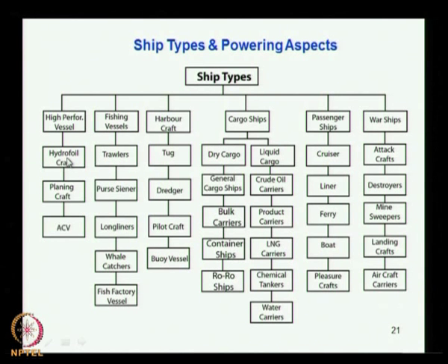When it comes to hydrofoil, again you have a displacement mode because initially it is fully waterborne. So it has to attain a threshold speed so that the velocity of flow to the underwater foil is sufficient to generate a lift and push the vessel up. So that power also should be estimated, that is the power required at the transition region, shifting it from displacement to foil borne condition. That means resistance needs to be estimated for different operating conditions to find out the power requirement, then to select the engine and then to design the propulsion system for that.